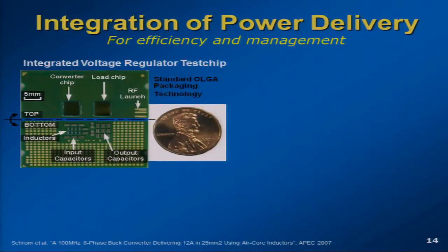This brings us to the next point. Well, I know how to control the power and the energy potentially given the hardware-software co-design. But that also means that I need to bring the power delivery closer to the load, and hence the integration of power delivery. If I can bring the power delivery mechanism closer to the load, then I can control that power delivery mechanism quicker, in nanoseconds as opposed to milliseconds today, and I can reduce the energy consumption.